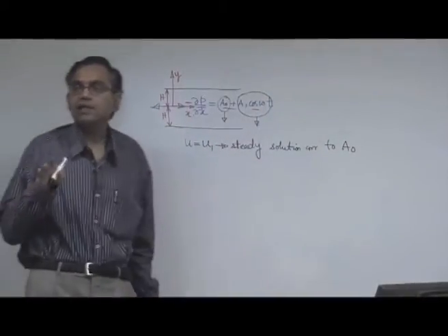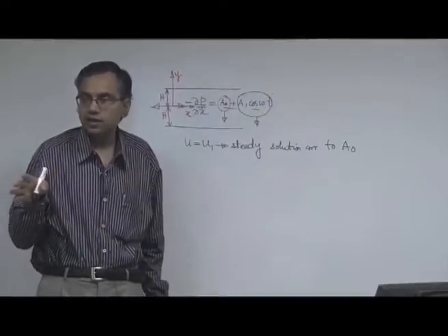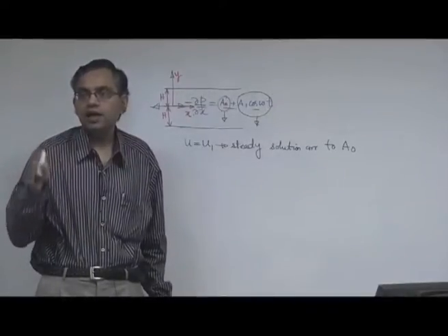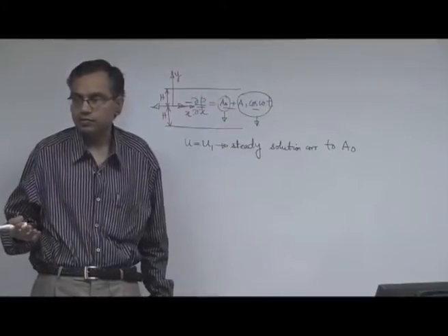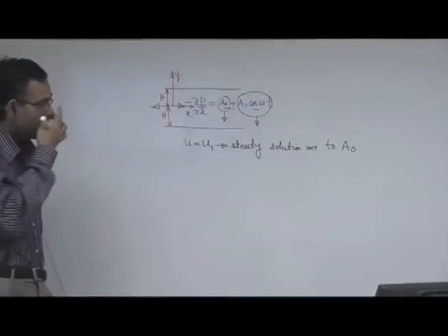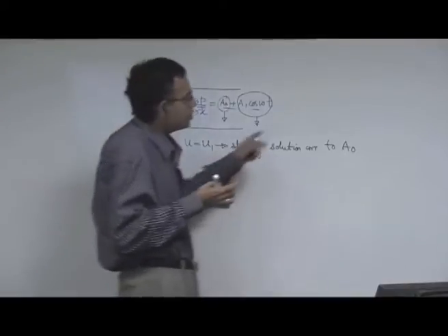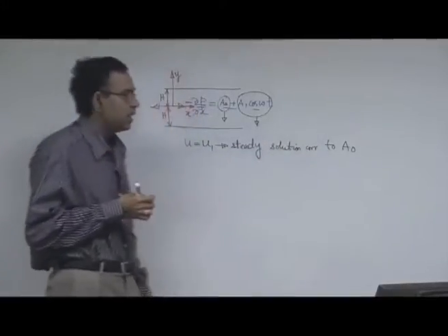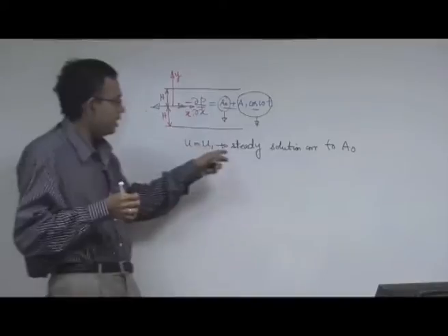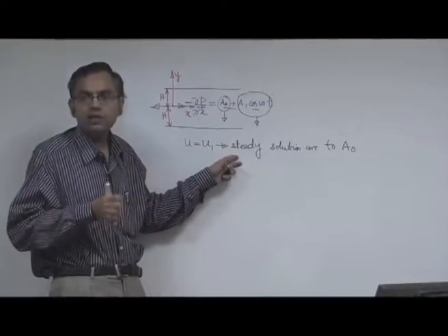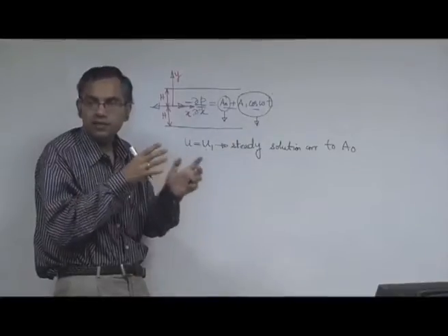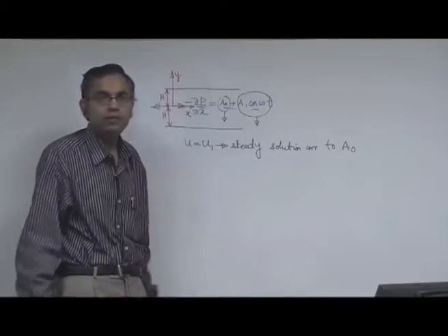That is, you apply a steady dp dx and you get the corresponding solution as a steady velocity profile. Okay. So, that is a steady solution corresponding to A0, and this we have already worked out quite some time back when we first started with fully developed flow through a parallel plate channel.